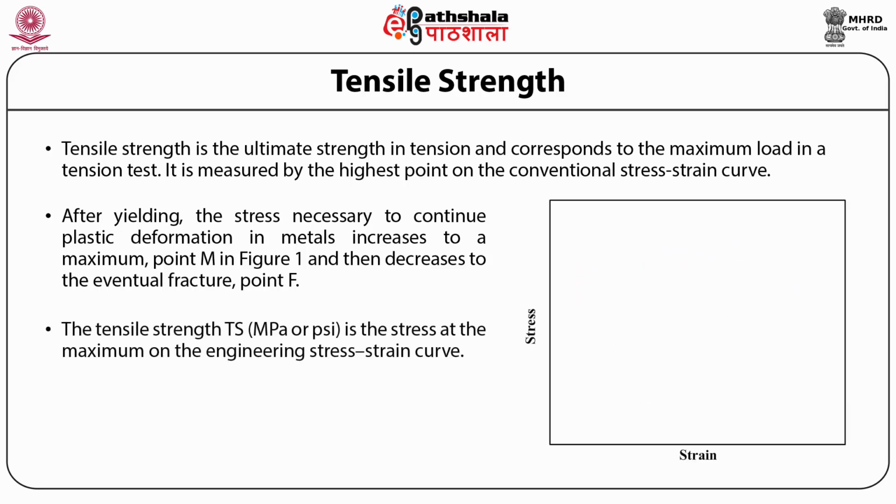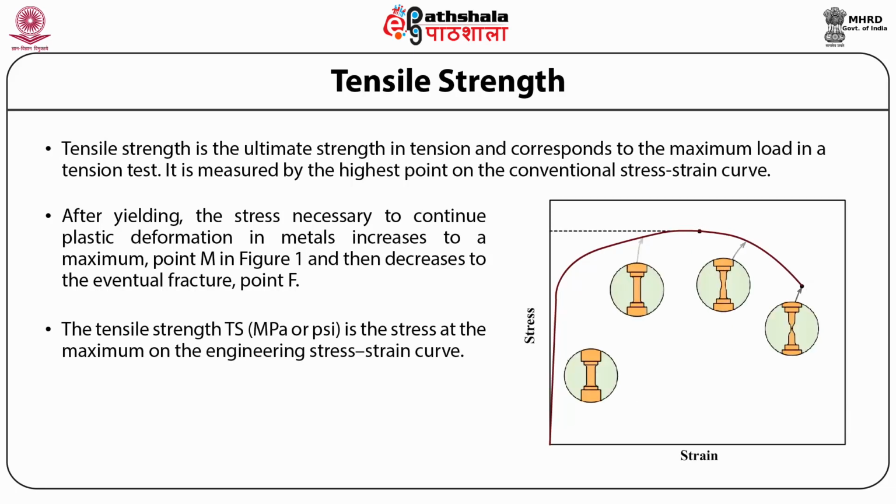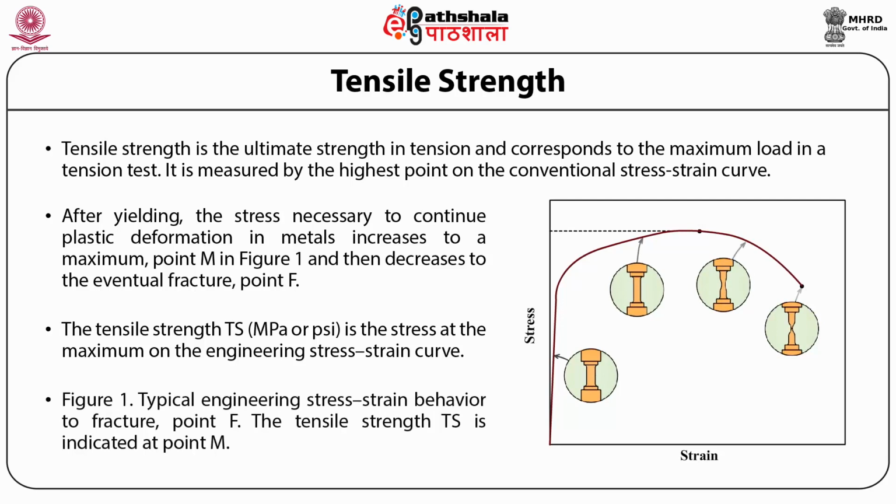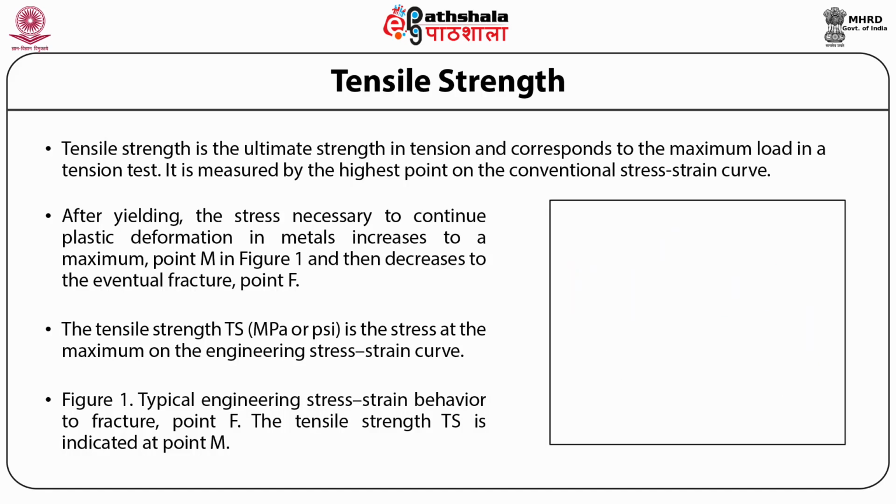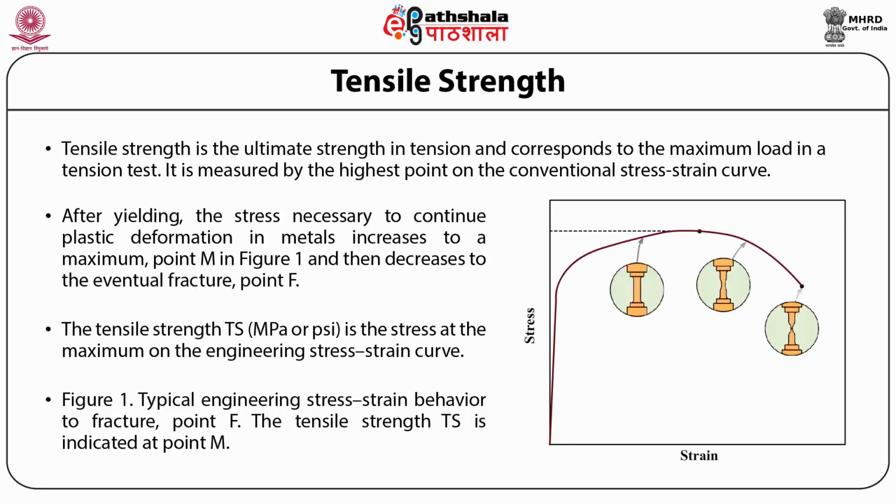The tensile strength Ts, in megapascal or psi, is the stress at the maximum on the engineering stress-strain curve. The given figure shows the typical engineering stress-strain behavior to fracture point F. The tensile strength Ts is indicated at point M.